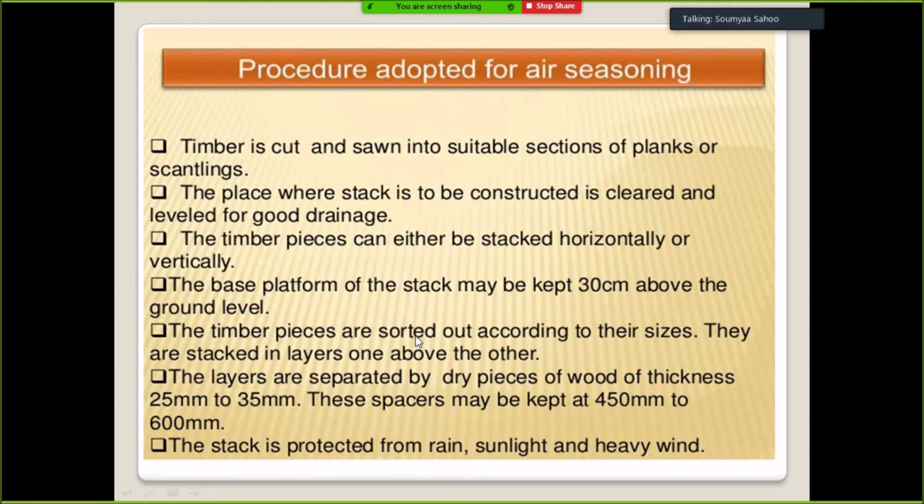The timber pieces are sorted out according to their sizes. They are stacked in layers one above the other. The layers are separated by dry pieces of wood of thickness 25 mm to 35 mm. These spacers may be kept at 450 mm to 600 mm. The stack is protected from rain, sunlight and heavy wind.